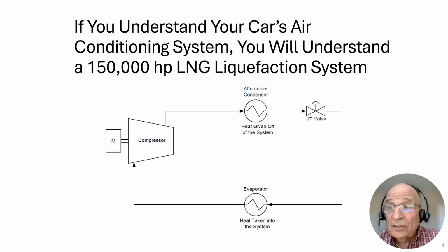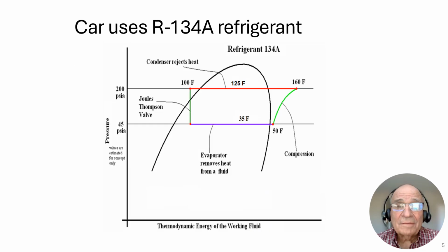Meanwhile, your air from the car comes into the evaporator at, let's say, 80 degrees Fahrenheit and leaves at 55 degrees Fahrenheit, cooling down your car. And then this refrigerant, which is 100% vapor now, because that refrigerant boiled off, goes to your compressor, and the cycle starts all over again.